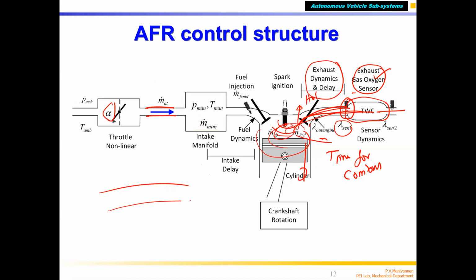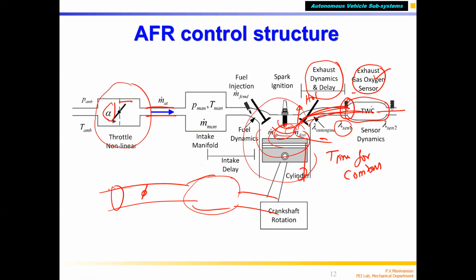The manifold is something like this, inside which you have the throttle plate. What should be the radius of this, and what should be the length? Then you have the manifold, where some amount of storing goes in. So you can find the dimensions of these things. Based on that and the throttle angle, the opening, you can find out the masses. You can vary the throttle opening and diameter using a computer program, without building the throttle, the engine, or having the TPS sensor.